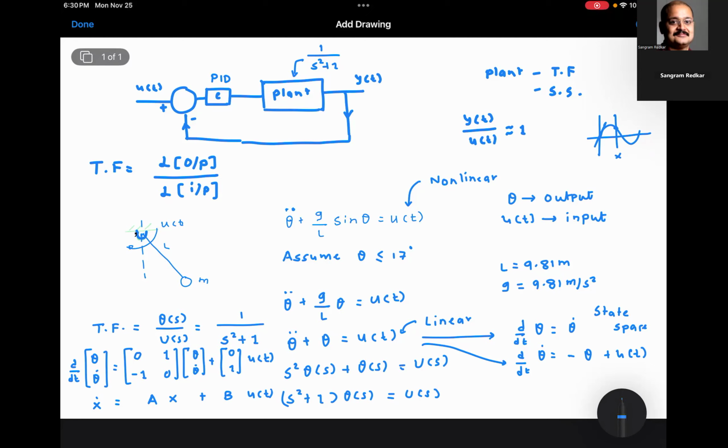What we do is we select all the outputs, we select all the inputs, and let MATLAB run its numerical algorithm to find the approximate linear relationship between some inputs and some outputs, and use those relationships to design the controller. So let me take you through this journey. It's very exciting, and this is exactly how you will linearize when you go to industry. Nobody does linearization by hand.